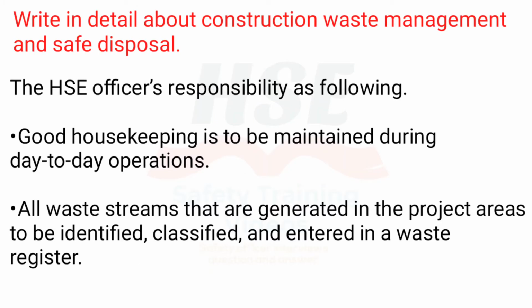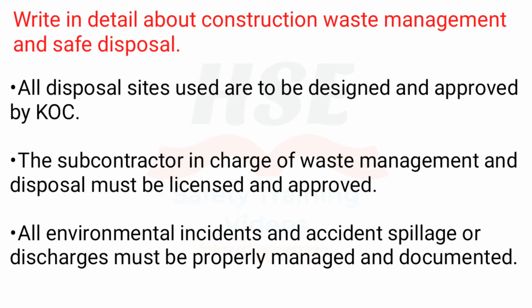Write in detail about construction waste management and safe disposal. The HSE officer's responsibility is as follows. Good housekeeping is to be maintained during day-to-day operations. All waste streams that are generated in the project areas are to be identified, classified, and entered in a waste register. All disposal sites used are to be designated and approved by KOC.